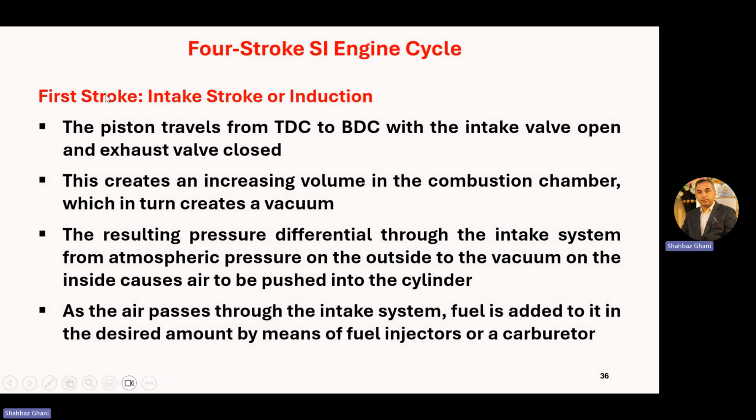Now, in first stroke, the intake stroke or the induction, the piston travels from TDC to BDC with intake valves open and exhaust valve closed. This creates an increase in volume in the combustion chamber, which in turn creates a vacuum. The resulting pressure differential through the intake system, from atmospheric pressure on the outside to the vacuum on the inside, causes the air to be pushed into the cylinder.